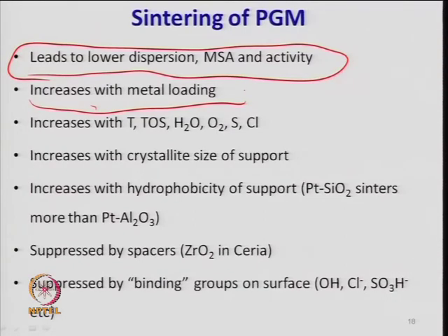Because of the larger metal concentration on the surface, there is more reaction when you have a high temperature condition. Temperature, time on stream, water, oxygen, sulfur, chloride also affect the performance, the crystal size or dispersion, when you give the heat treatment. So this should be avoided. A definite temperature is desired, not more than a certain level, that you have to tune or check. Same thing for time on stream.